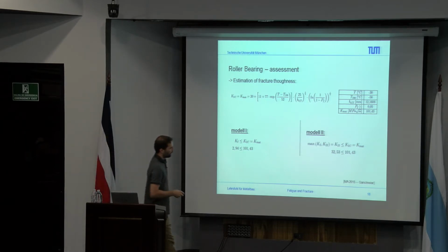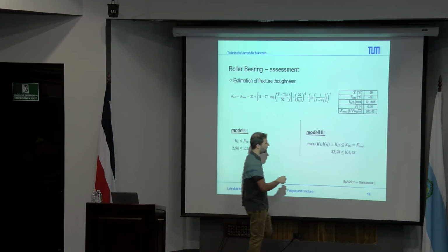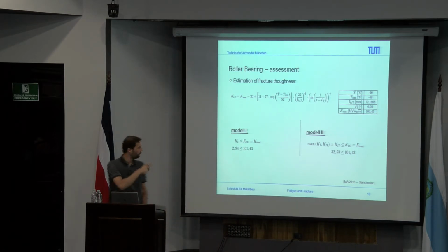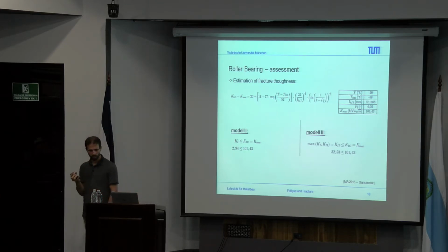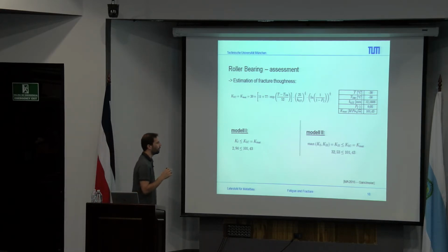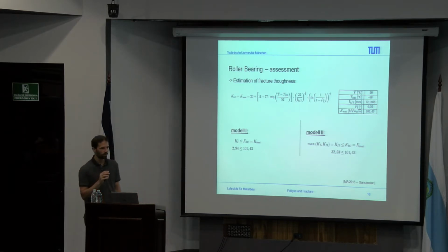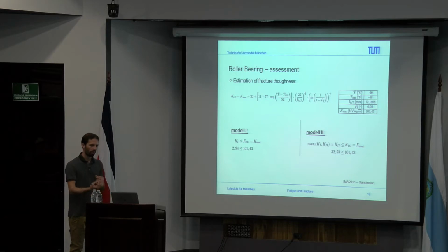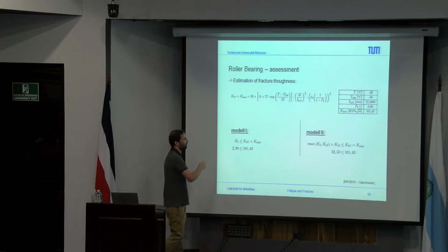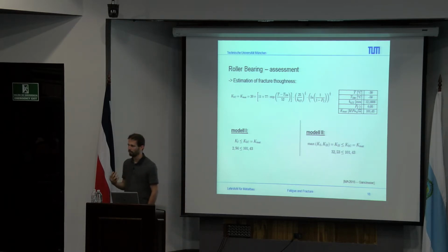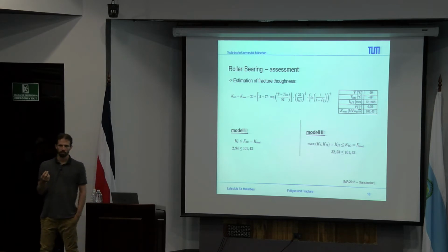So, how was the K1C defined at the end? The K1C is defined by this formula above, and this is just a rough estimation of the fracture toughness. And this fracture toughness at the end is defined due to some Charpy tests. And in this case, it was also possible due to the materials. So for some materials, there have been some enhancements to define some empirical models for the K-mat.